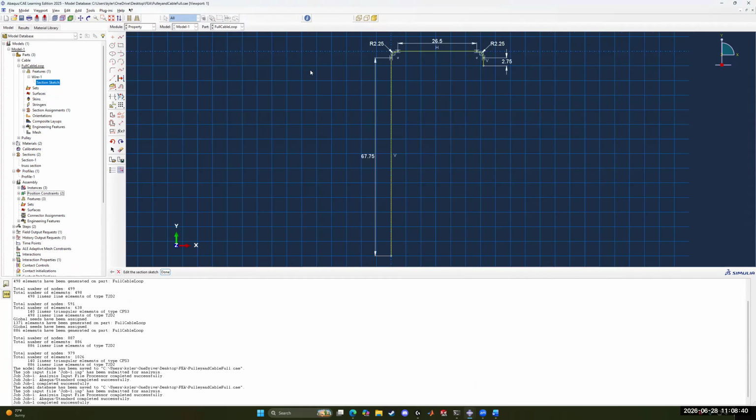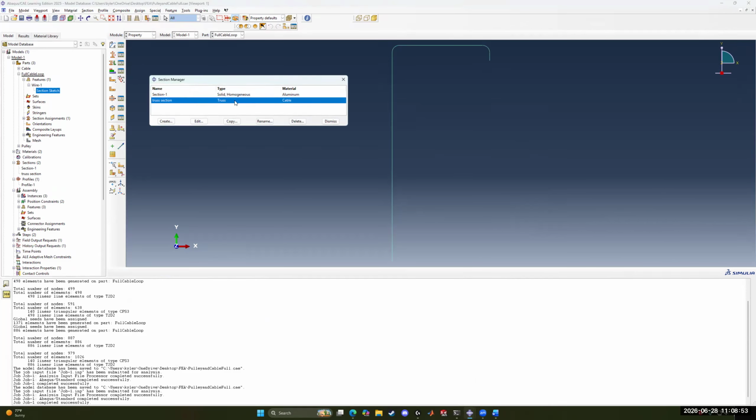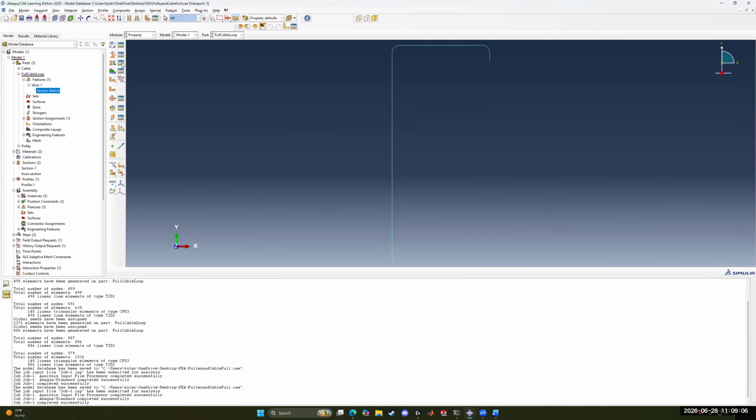So second method: when you want to add more pulleys to your system, you need to switch over to using truss elements. So this is how I design my cabling system using two pulleys here. You're going to use the same properties. When you're creating your section for your new cabling, make sure you select the type as truss elements. Now you're going to have to calculate and add your cross-sectional area directly using the diameter of your part. There's no need for that beam orientation anymore.